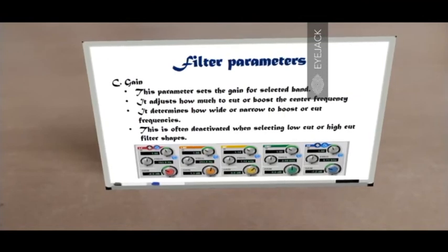So if you look at the picture carefully, the bottom line represents the gain. I don't know if you can see the values, but surely you can see the knobs. The knobs are pointing way down at the low frequency and the high frequency, and they're negative, minus 6.8 and minus 7.2 dB, whereas the low mids, the mids, and the high mids are positive, which means they're going to be boosted, whereas the low frequency and high frequency are going to be attenuated.